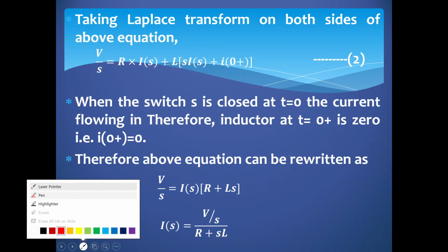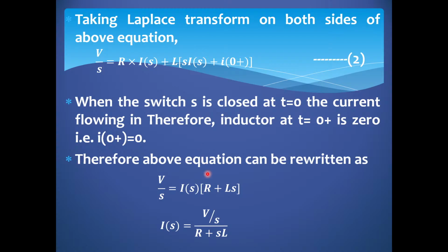Am I telling it in the reverse way? Does an inductor act as a short circuit or an open circuit? If no current is flowing, that means it is acting as an open circuit, isn't it? I think instead of using the term open circuit, I was using the term short circuit. Yeah, I'm telling it in the reverse way. So as soon as the switch closes, the inductor won't act as a short circuit, it acts as an open circuit.